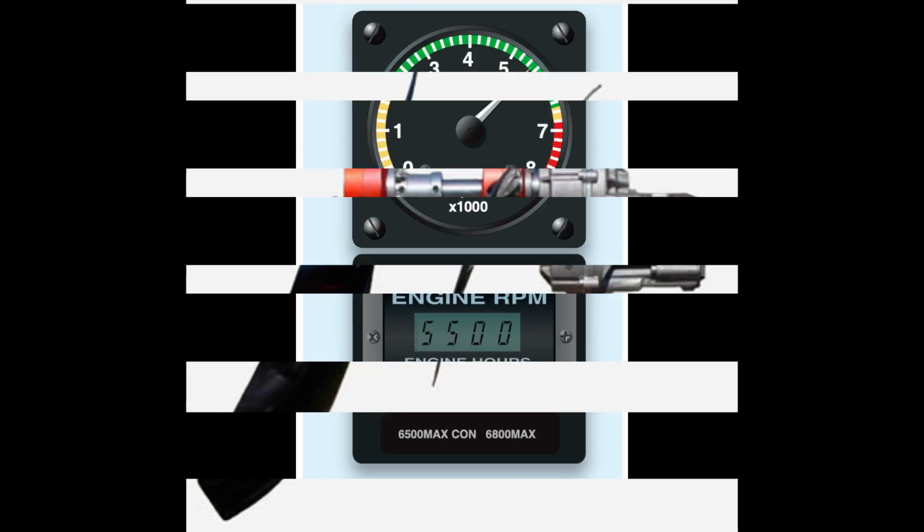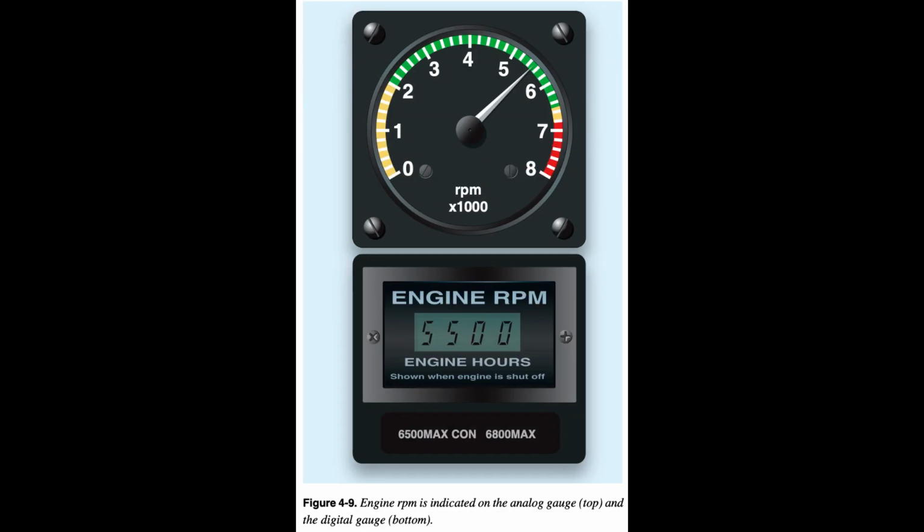Propeller. The propeller provides the necessary thrust to push the WSC aircraft through the air. The engine power is used to rotate the propeller, which generates thrust very similar to the manner in which a wing produces lift. The amount of thrust produced depends on the airfoil shape, the propeller blade angle of attack (AOA), and the engine RPM. Figure 4.9.